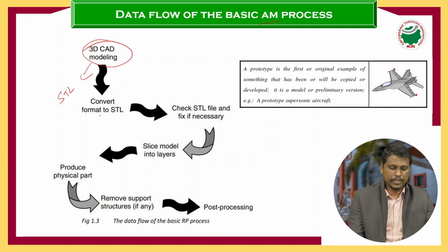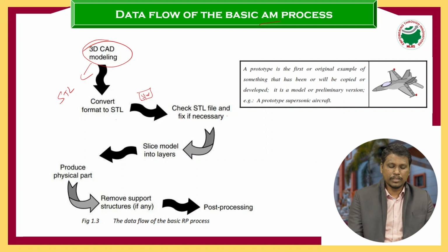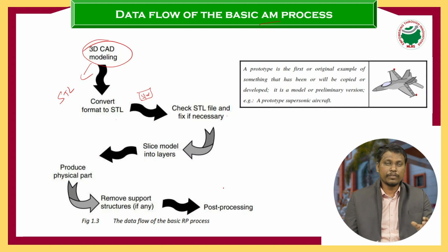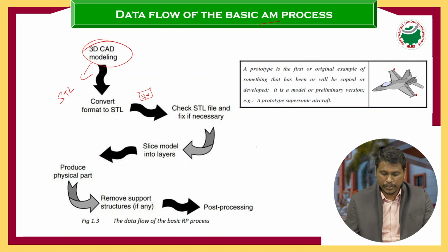After converting to STL, we have to send that STL to particular software that supports STL files. Okay, the best example is Cura software. After sending this 3D design to that software, there we can see the full diagram of our design. There we can check whether any unclosed elements are there or not. Unclosed means, for example, you can see this square cube I am drawing.